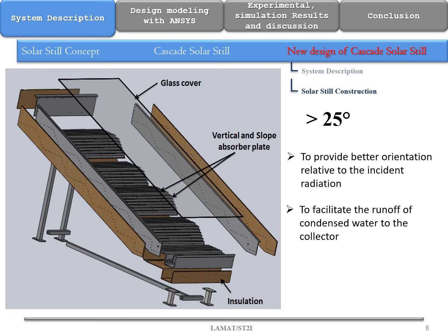The basin is made of metal, aluminium, and the thermal insulation is achieved by coating inside the basin. The absorber plate is made of aluminium and painted black, consisting of horizontal and sloped surfaces with black metal baffles on the inner face.